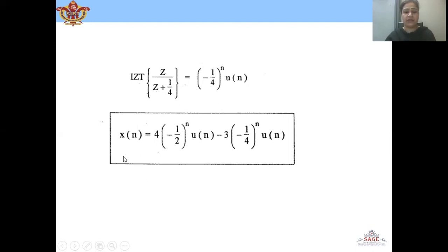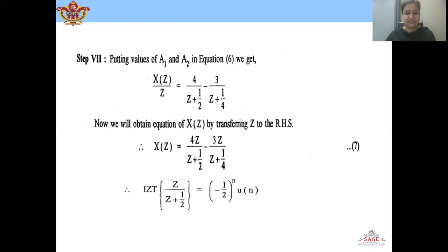Here we have calculated the inverse z transform of X(z), which is x[n]. Now, if we calculate the inverse z transform depending on the ROC, say here we have assumed that the ROC is |z| greater than 1 by 2. So, both the sequences will be causal here.